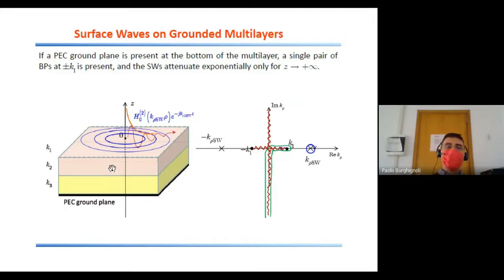This is the situation that is typically found in microwave integrated circuits, in which we have a metal ground plane and some upper medium, typically air or vacuum. If you have just a single layer of dielectric, you have the typical substrate for a microstrip line, for example. But in general, you may also accommodate a general stratification involving more than one medium.